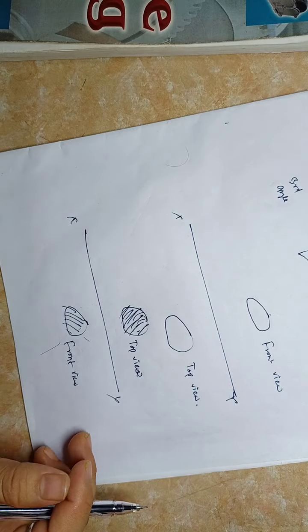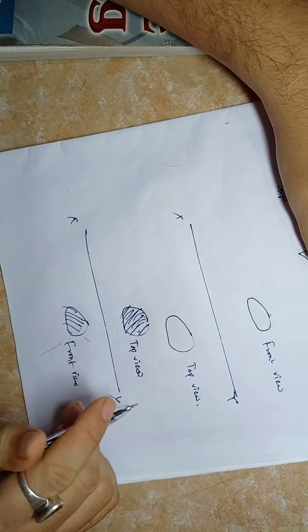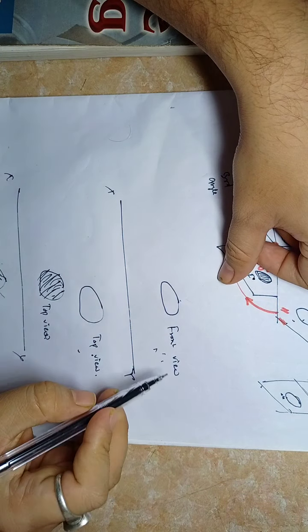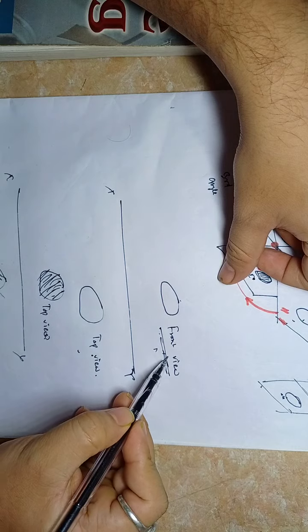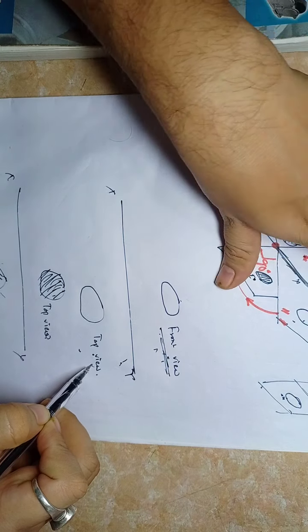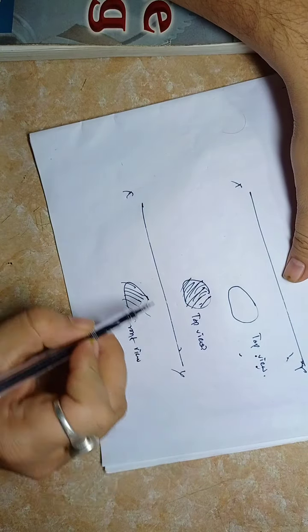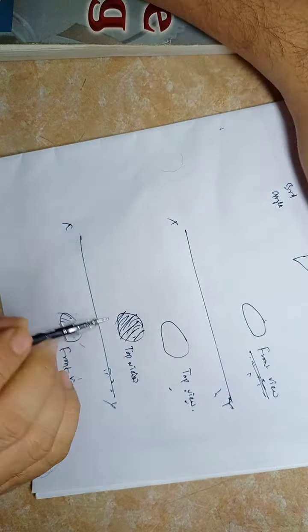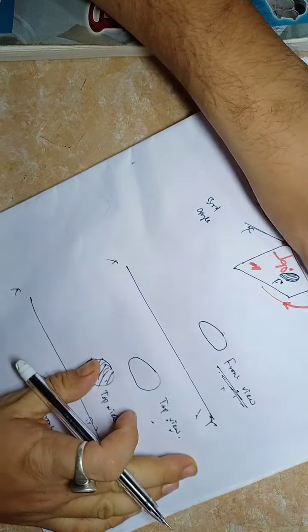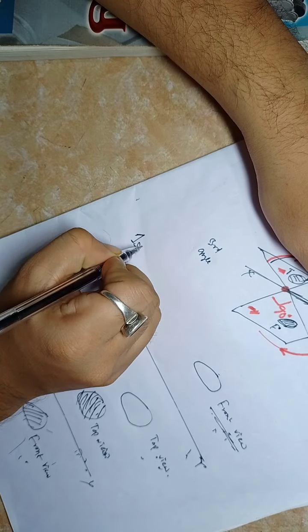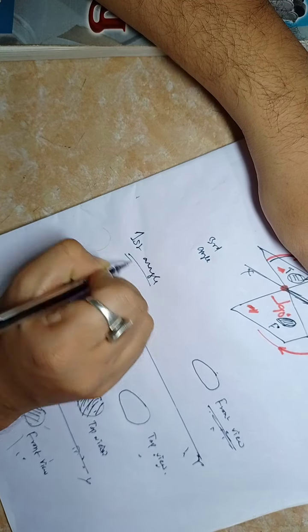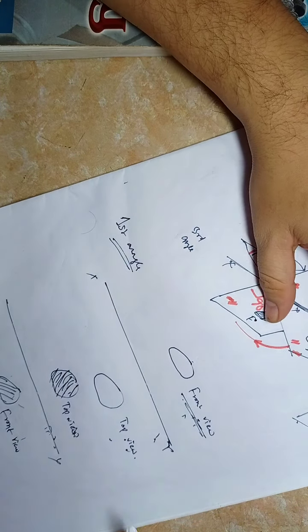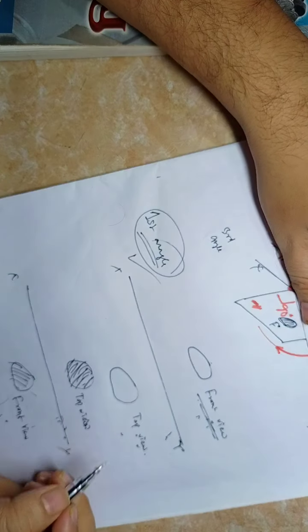Okay, fine. Now you see what is the difference. Now we have seen, first of all, in first angle, front view is above XY line. Okay, top view is below XY line. And for third angle projection, top view is above XY line and front view is below XY line. But for your help, you always please follow first angle projection throughout your diagrams, your class assignments, and your exam. In your exam also, please follow first angle projection.